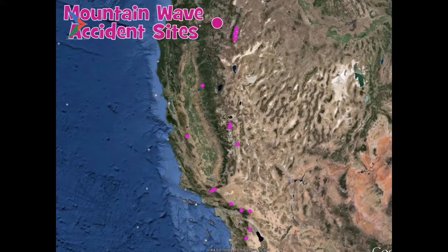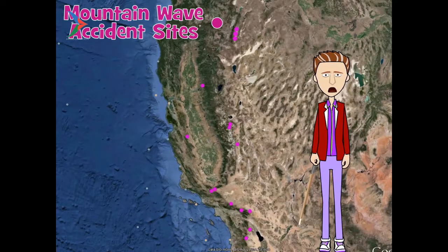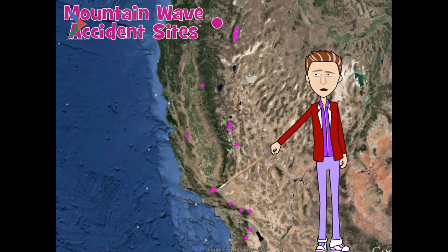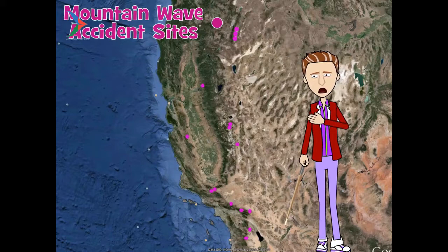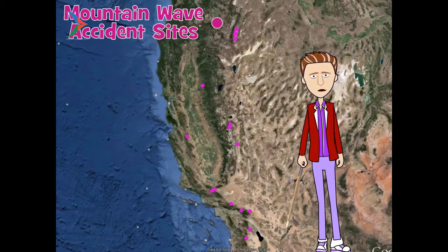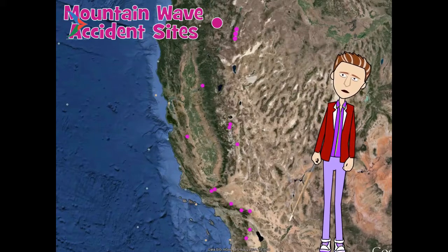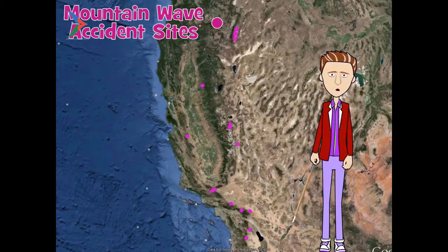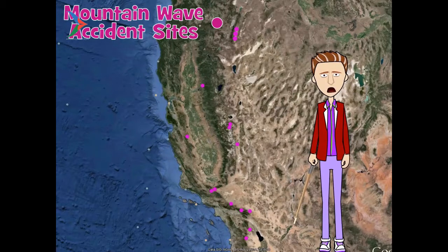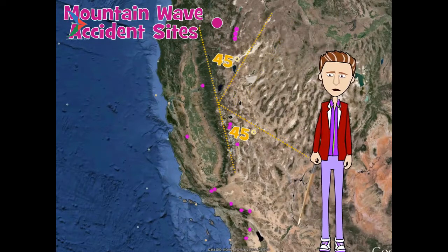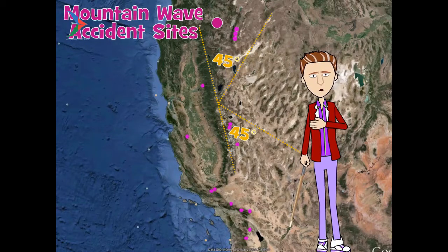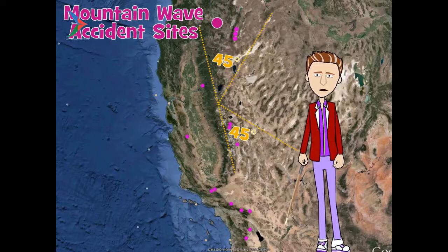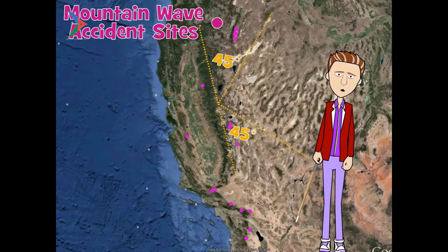Now, I don't want you to walk away from this presentation thinking, oh my gosh, I will never operate over a mountain range. No. That is not the lesson I want you to learn here. What I am saying is to use caution and use a defensive strategy when approaching any mountain range, in particular one where you might not know what the wind velocity is over that range. Therefore, when you approach that range, you approach it at a 45-degree angle. That allows you to turn away from the mountain range through an arc of 90 degrees rather than an arc of 135 degrees, which is what you would experience if you approach that mountain range at a 90-degree angle. It's just a good defensive strategy.